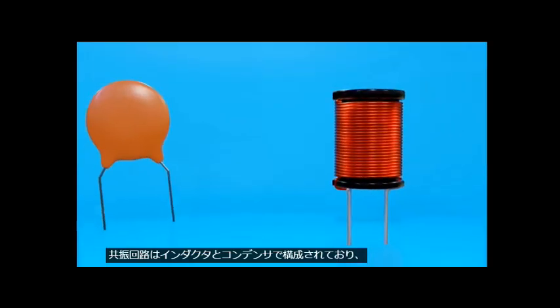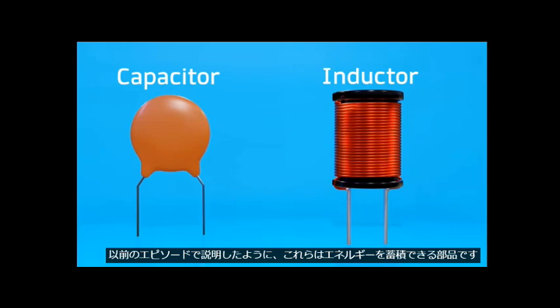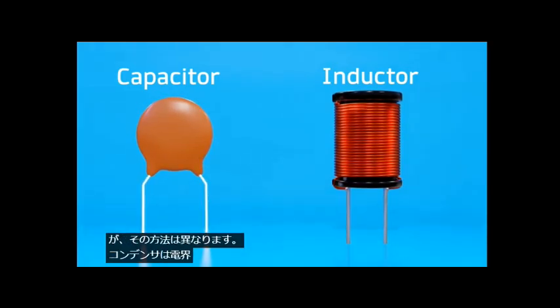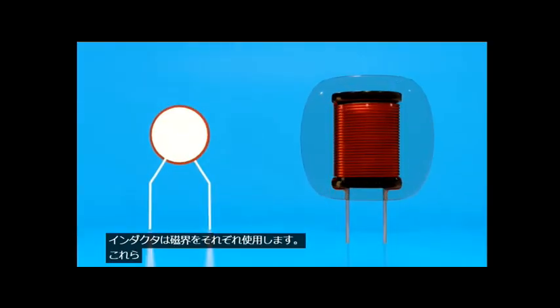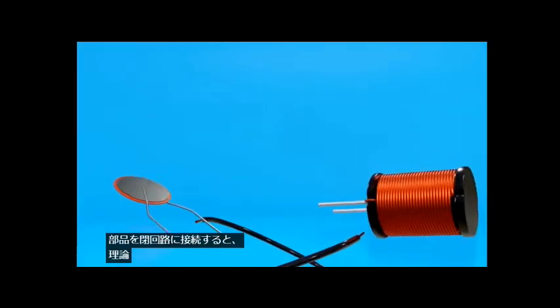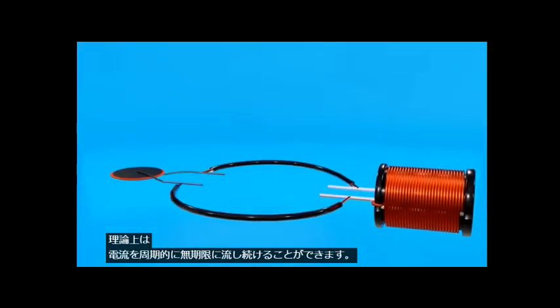A resonant circuit is made up of an inductor and capacitor, which, as we have seen in previous episodes, are components capable of storing energy, although they do it in a different way: the capacitor with an electric field, and the inductor with a magnetic field. The effect of connecting these two components in a closed circuit is that, in theory, we could keep an electric current flowing cyclically indefinitely.